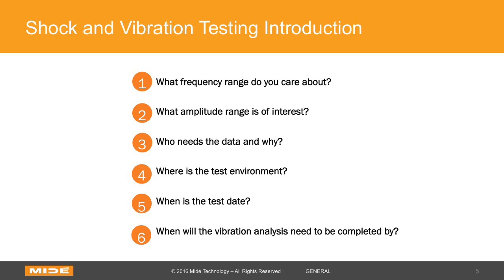Who needs the data and why? A lot of you guys will be doing some testing for the U.S. Navy or some other military group. There's a lot of test standards out there, like Mil Standard 810, general environmental things, and then 901Ds for shock. You'll see a lot. But these test standards can be something that you should look at before you set up the test, because actually a lot of the standards will go through sensor selection and various things and best practices to use. So it's good to understand what you're doing it for.